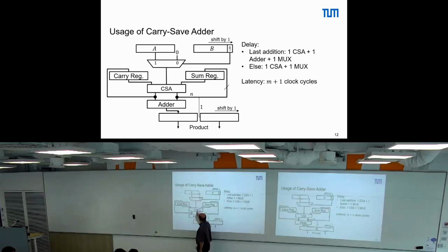So if I remember correctly, which gives us the carry bit here, right? So three input bits are converted. We connect one here, one here, one here. So these three input bits are converted into one sum bit and into one carry bit, right? All the time. And at the end, we need to sum up all these carry and sum bits, right? So that we have one binary representation again.